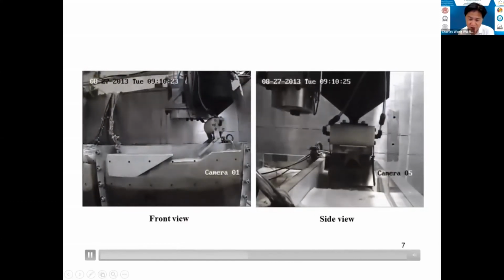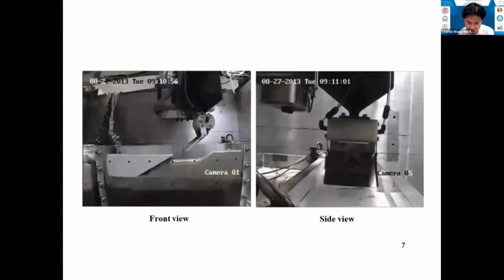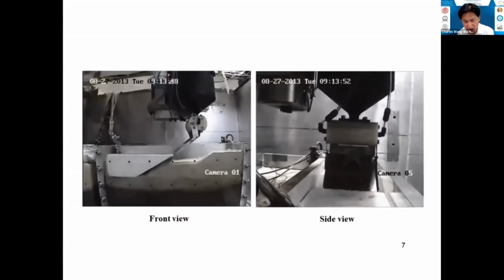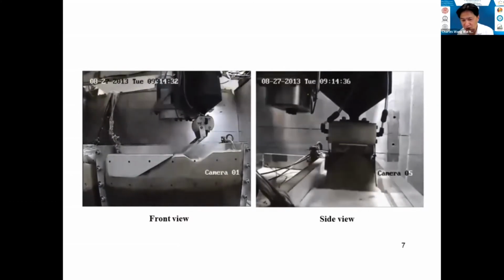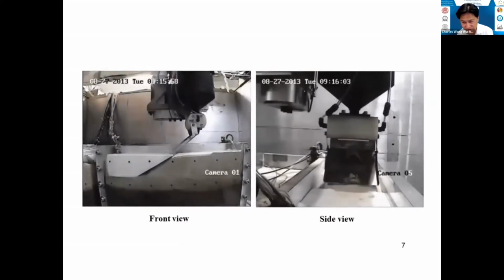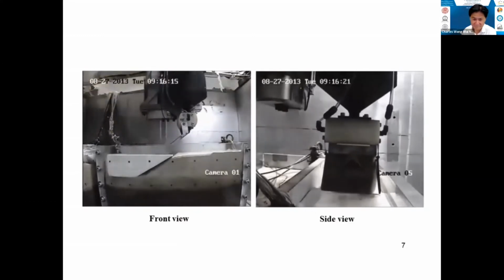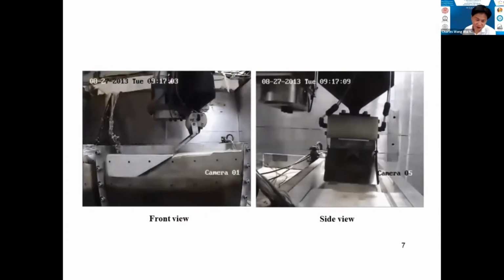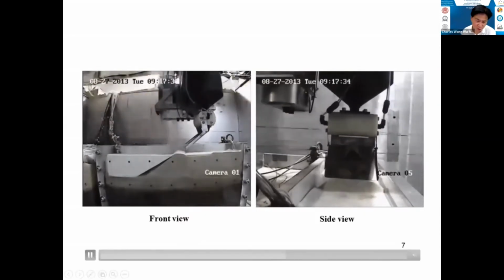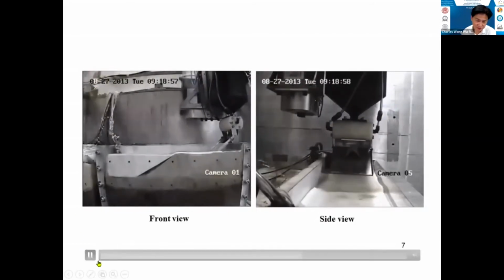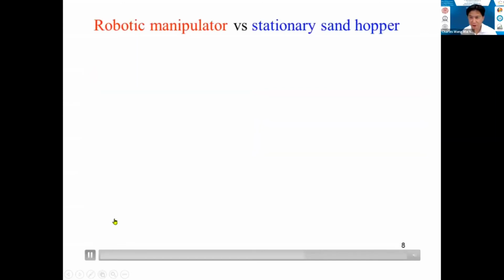so that we can properly control the speed of the construction in a centrifuge, which will mimic what actually happens in the field. And also we can control the density of the filling material in a very precise manner by using a robot. This is almost the final touch of the construction. During the construction of the new part of the embankment, pore pressure, soil strain and bending strain of the piles were monitored. I will skip that in the interest of time.